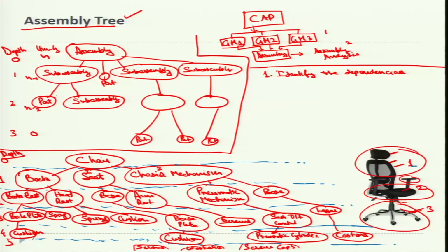So, identify dependencies means whether the assembly components are individual parts or entire sub-assemblies. That is, does it consist of other sub-assemblies or parts or not. Identifying these dependencies or interdependencies helps us determine the best approach to create the assembly. The bottom up or top down or any approach could be followed depending upon the system that you have to develop. Bottom up approach would be starting from the very component level going to the assembly level. Top down would be considering the overall assembly to be manufactured, then we come down to have the components of it.